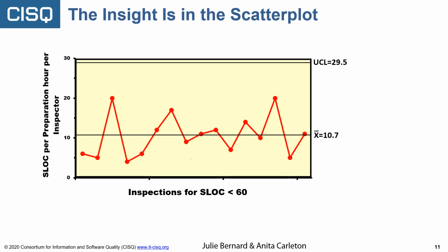If I look at a scatter plot and treat it as a scatter plot, it begs me to ask questions. And so what I'm suggesting is that, okay, you can do statistical process control if you have to, but the fact is, look at the scatter plot and ask questions, because you're going to find assignable causes, and that's the key to getting control. If I wanted to have control charts for this process I've just shown you, I have to have a minimum of 3, and it could be more. Well, for every process, the last thing I want is 6 control charts.